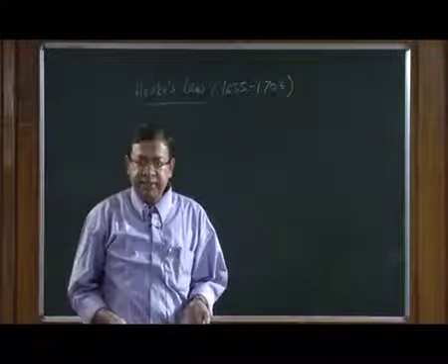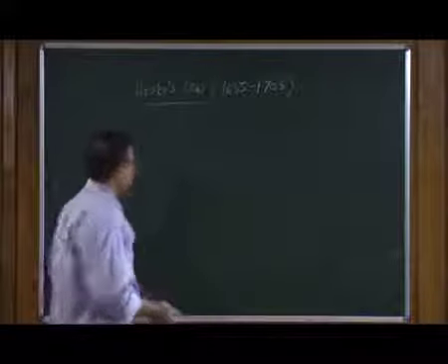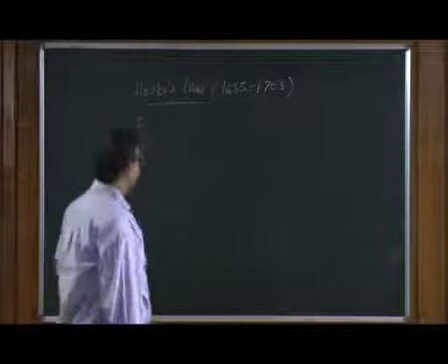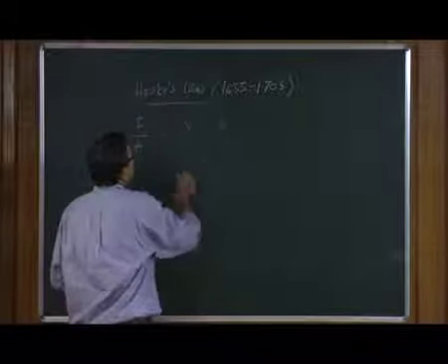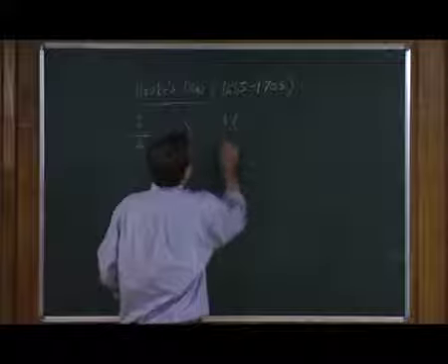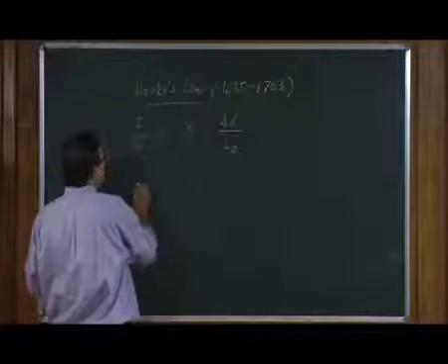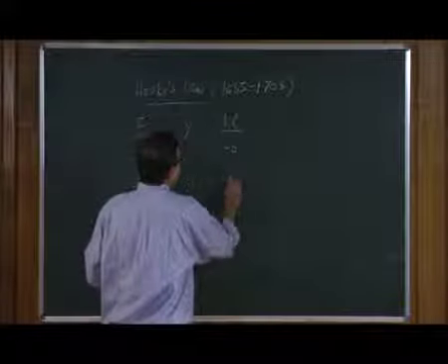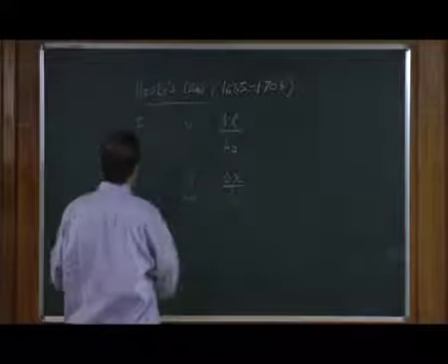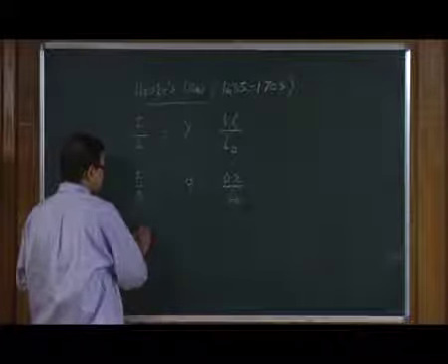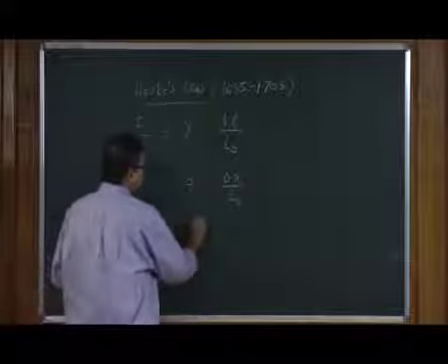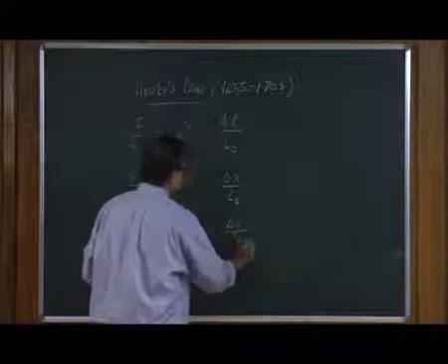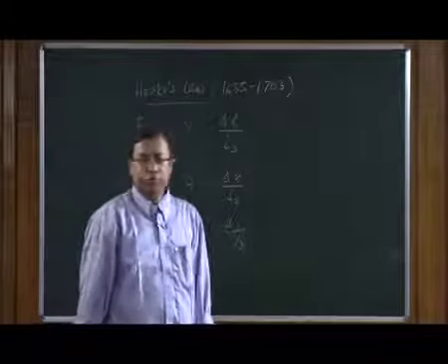This is summarizing the findings that we have so far, and we can write for the first case of the tensile stress and the tensile strain, we had delta L over L0 connecting to F over A, and similarly the F over A is connected to delta X over L0, and finally this delta P, which is connected to the bulk modulus by delta V, and just in accordance with this L0 we will write a V0, which represents the original volume of the system.